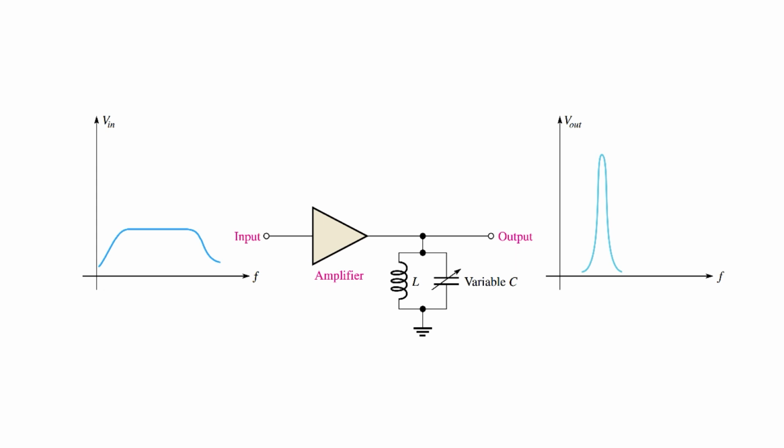One such application is in your radio. The signal carried by the electromagnetic waves is detected by your radio through the antenna. This signal is very weak and needs to be amplified. It also contains a lot of unwanted signal, which is why you need the tank circuit to act as the bandpass filter. When you dial the knob, you actually change the value of the capacitance in order to tune to the station you want to listen to.